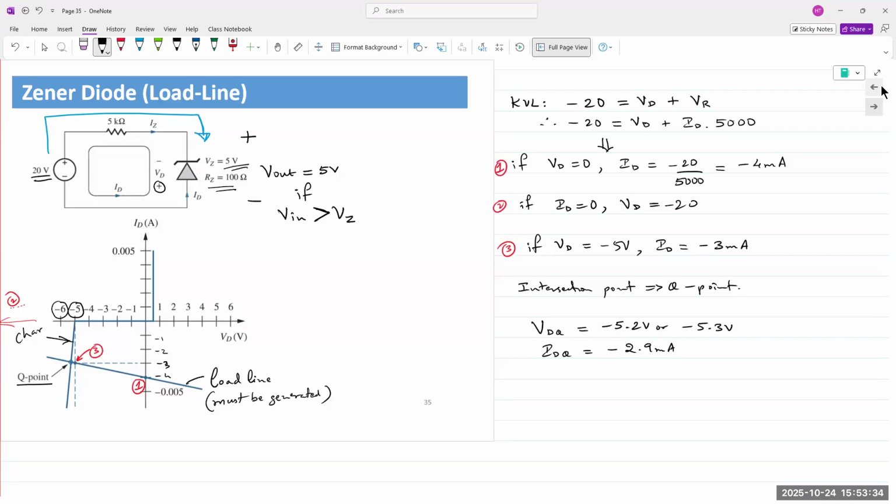And for a Zener diode, we always use Zener diodes in reverse bias. And so VD technically in this case would be minus VZ. Yeah. So sometimes it's tricky. When I was a student learning this for the first time, it took me a hard time trying to get my head wrapped around everything. It's just a sign convention. That's all it is, just because it's in reverse bias.